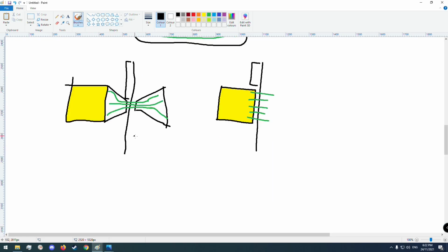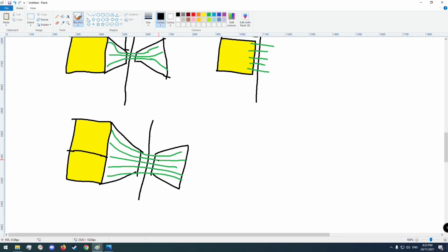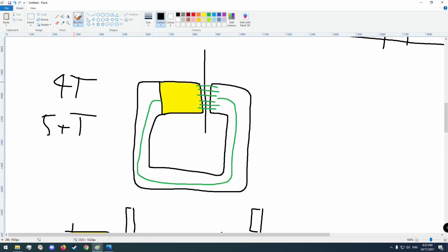This can also enable you to create a situation like this one right here, where you actually double the amount of magnetic field going through the voice coil and have the same excursion. Although cases where you see 4 Teslas or 5+ Teslas are incredibly rare, and the most common field strength you'll come across is from about 0.6 Teslas to a max of 2 Teslas, which is from a steel alloy.